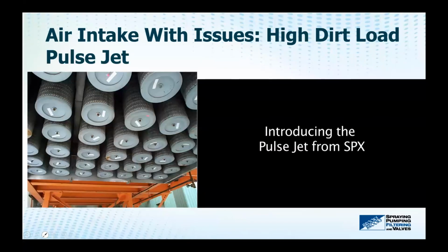Another method for high dirt level locations is pulse jet filters. So they're self-cleaning. We've installed some of these in Saudi Arabia, which was one of the locations for dust storms. And they're self-monitoring. They clean themselves. So sometimes they don't have to work at all because the conditions are clean, but if dirty conditions arise, then they would clean themselves. And if I get this right, we can show a little animation. And if you have headsets on, I'd recommend you potentially take them off.